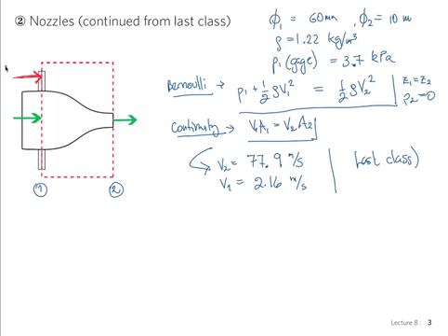The other force working on the control volume is of course the pressure, P1A1, applied here. P2A2 is 0 because we're working with gauge pressure. That's the advantage of using gauge pressure for such a system, and also the advantage of choosing your control surface wisely by crossing the jet at the point where it's at atmospheric pressure. Make sense? Okay. So P2 is equal to 0. Are you guys following me? Okay.